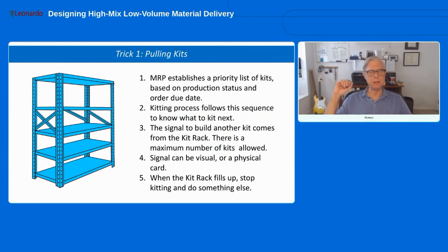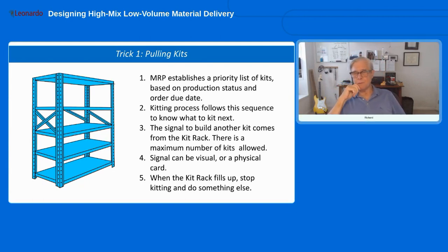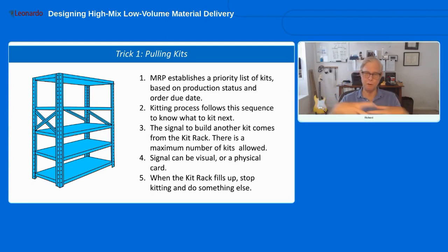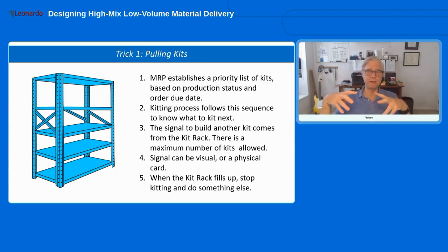Okay, so a couple of tricks. We're getting close to the end here. We have time for, I know some of you have been asking some questions, so I want to allow time for that. One thing, especially if you have remote kitting, one thing we ran into when we arrived at this one company was they had tons of kits that were being pushed onto the floor. In other words, the kitting department, before we arrived, had a rule: look at the schedule and try to get the kit for these different orders prepared at least several weeks ahead of need, right? Keep ahead of it. And so they prepared a kit, and what did they do with it? Well, they didn't hold on to it. They just delivered it to the factory floor.